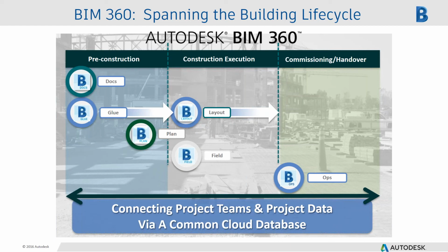So via BIM 360 Glue, syncing up an iPad to a total station, like a Topcon, out in the field to lay out construction points, whether it's footers, hangers, whatever the case may be. Laying all of those out with the model information tends to be highly accurate and can certainly be utilized for QA/QC purposes.